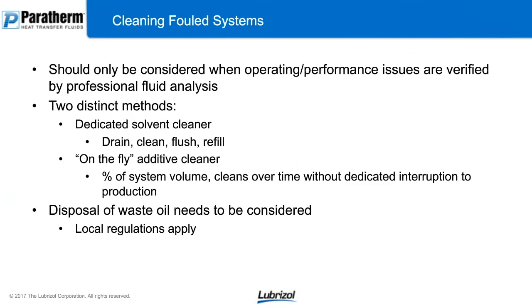So if you do have an issue with fluid analysis, you should really make sure you verify that with your fluid analysis program. There are two distinct methods to clean it. You can fix those cold spots by a dedicated solvent cleaner or an on-the-fly additive cleaner. Just make sure that any disposal of waste oil needs to be considered. All local regulations are different in how they treat waste oils. If you have a synthetic product, it could be even more different than that. So really work with your thermal fluid manufacturer and supplier when you're dealing with cleaning and recycling oils.